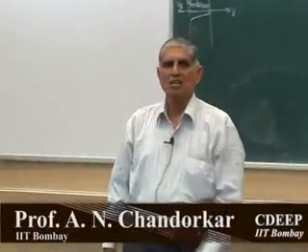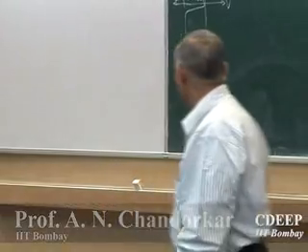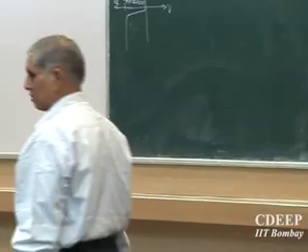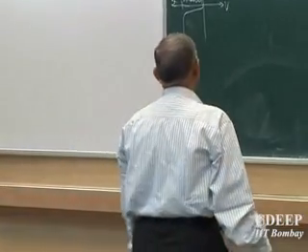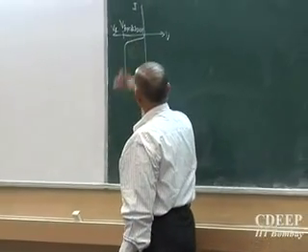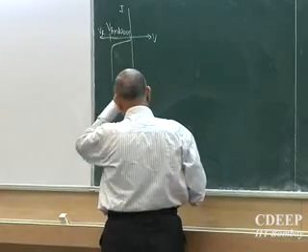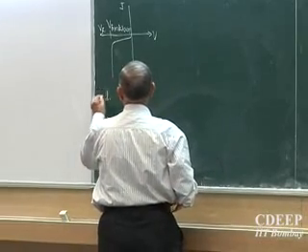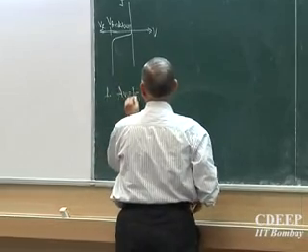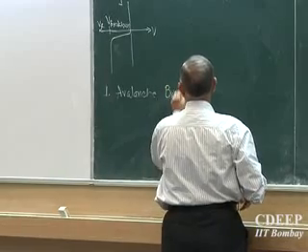At that time the current may reach a very large value, typically it can go to amps, and if the device is not heat protected it may even burn. So why is such a characteristic seen, that at a certain value of V breakdown we see large currents? There are three mechanisms which I said. One of course is called avalanche, the word suggests something, avalanche breakdown.